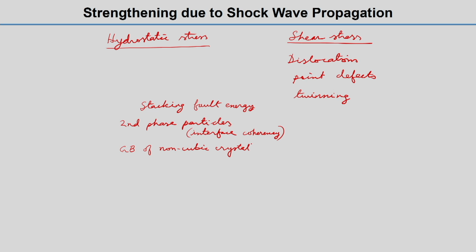Hydrostatic stresses affect that, and also phase transformation, like our martensitic phase transformation, is mostly affected by hydrostatic stress. And then recovery and melting, or you can write melting point, is affected by hydrostatic stress.